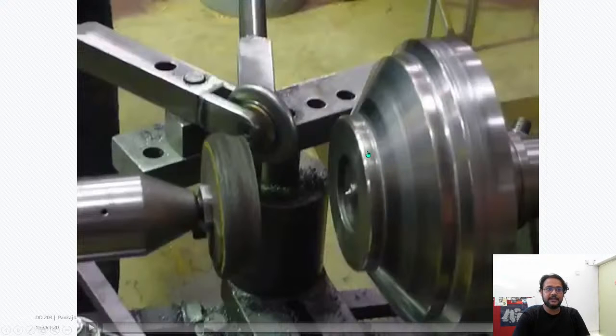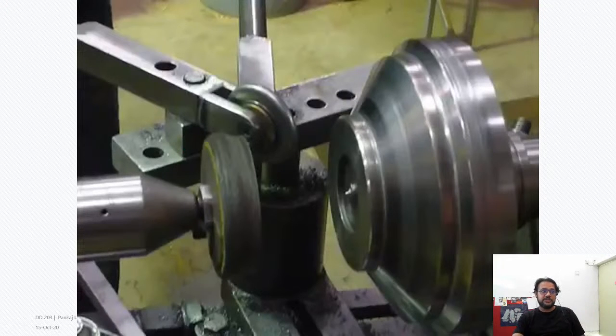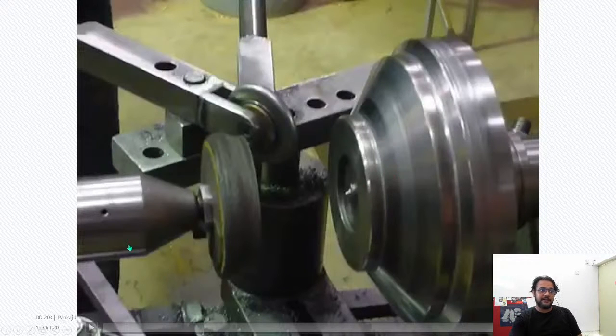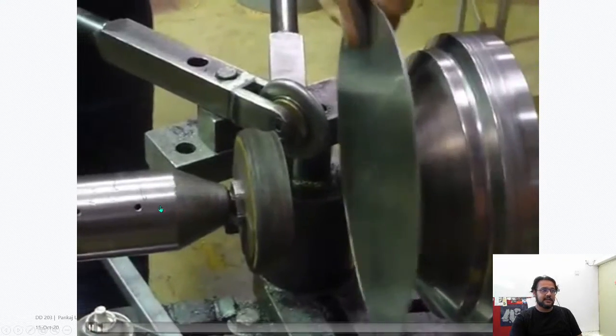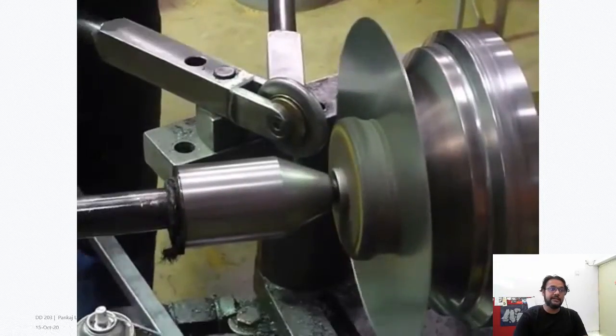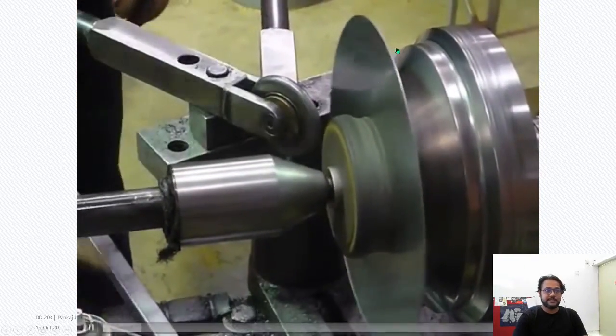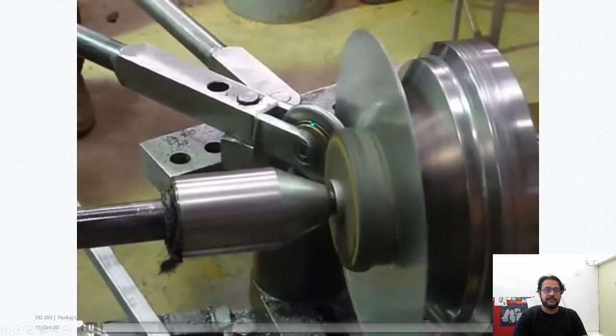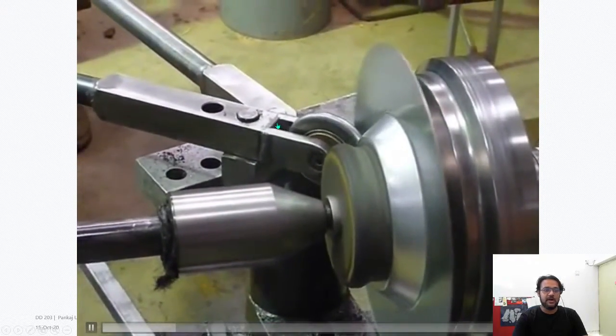Now this is the mandrel, and you want the sheet metal to take this kind of stepped cylindrical form, and this one probably will be part of a light fixture. This is the tool that I'm talking about. It's like a donut shape, and this tool is mounted on a structure. This whole operation can be done on a lathe machine with the proper attachments like these mandrels and this tail stock. And you'll see that it's a fairly labor intensive process. This is a lubricant that is put in so that it, so you see how it kind of,